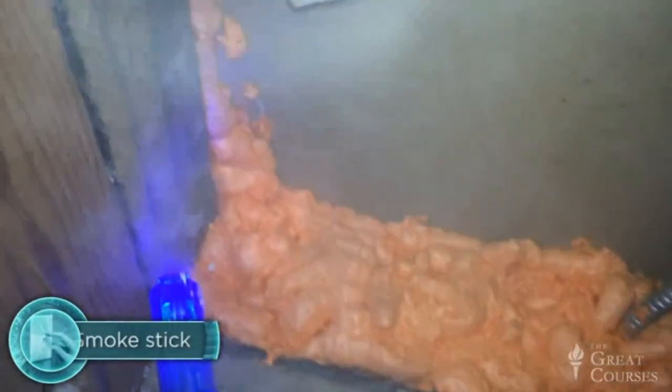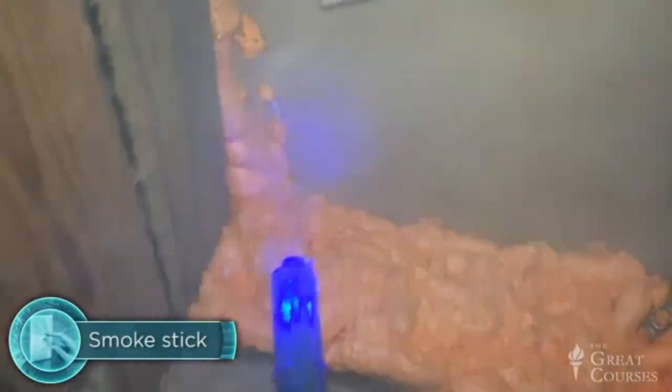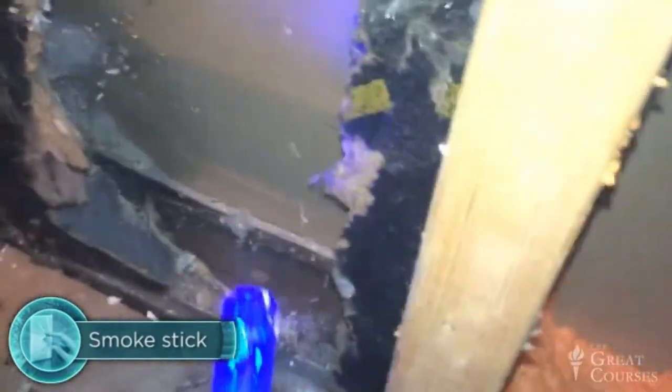This air movement is then easily detected with a device called a smoke stick, and the gaps can then be identified and plugged. When used on a completed house, the blower door test can provide valuable information for an energy audit, but it's even more valuable before that interior drywall has been installed, when leaks can be more easily sealed.